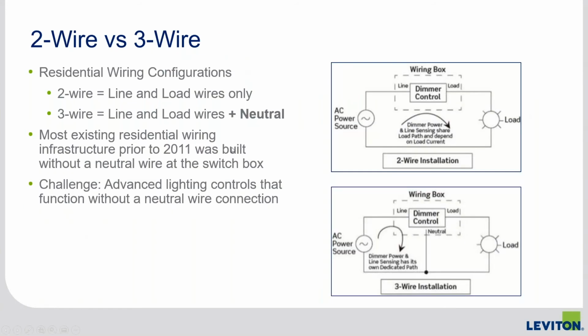So taking a step back from the bulbs or fixtures and talking more about the dimmers, we have a major comparison point between what you're using and when you're using it. And that really comes down to if you have a neutral. When we talk about neutral wires, we say we have 2-wire dimmers, we have 3-wire dimmers, but when you boil it down, that's really what we're saying.